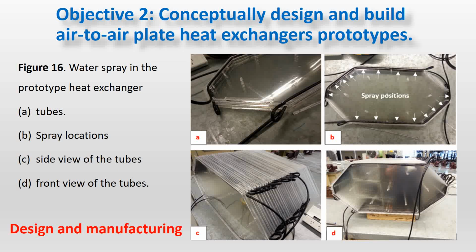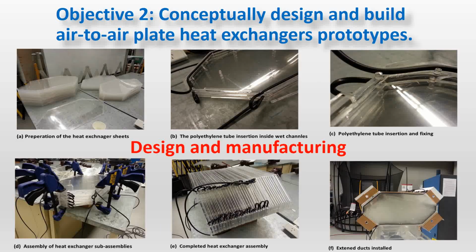I tested earlier outside and this gave me the results required, and I tested at each stage until I finished the work. Actually, I spent the Christmas holiday doing that. I was alone working at level 10 at the UTS, me and the security. So these are the stages of building the things, preparing all the heat exchanger plates, stacking them on top of each other, fixing the tube inside the heat exchanger channel so the thing is going to move due to the pressure of the water. I added the extended ducts for more accuracy for the water spraying and the measurement.